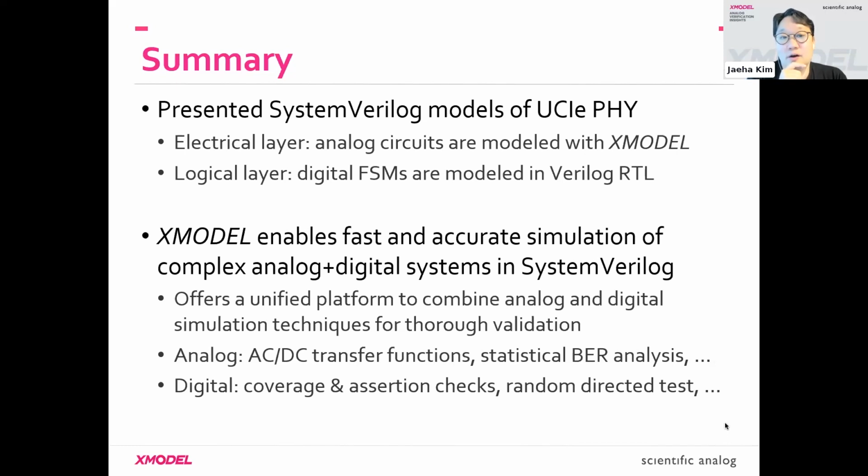Even digital, which is addressing a way bigger circuit than analog today, they're not doing that. They never expect a single simulation to verify everything, including all the non-idealities. What they do is break the whole set of verification tasks into a set of small tasks, and they do it one by one using a method that's most optimal for each task: timing analysis, cross-coupling analysis, power analysis, functional verification.